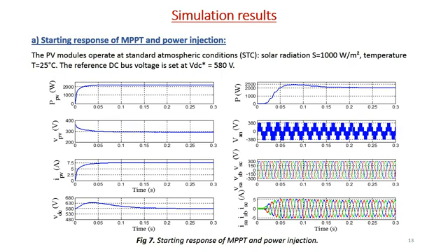The DC bus voltage is well controlled by governing the injected power. The inverter output voltage shows 5 levels produced by the optimum voltage vectors selected by the predictive current controller. The output currents have sinusoidal waveforms and are synchronized with the grid voltages.